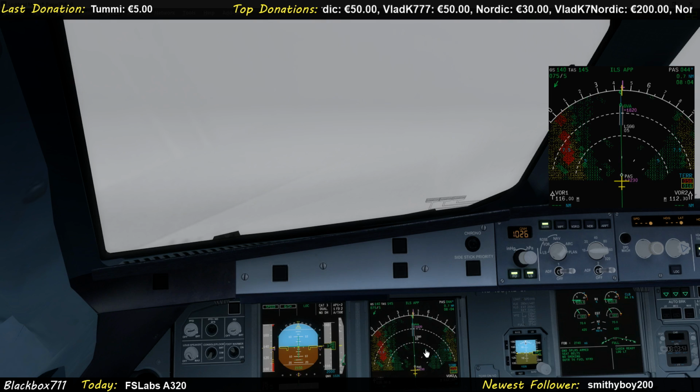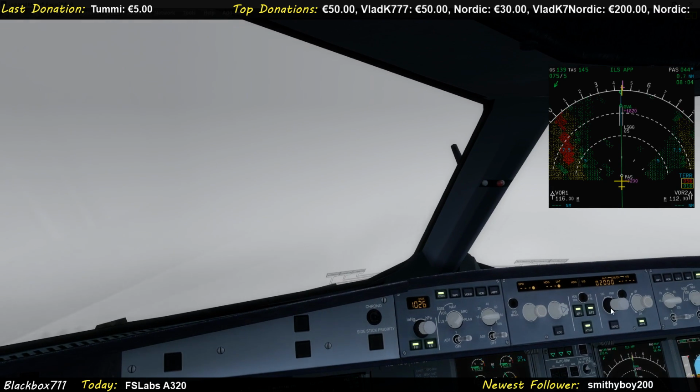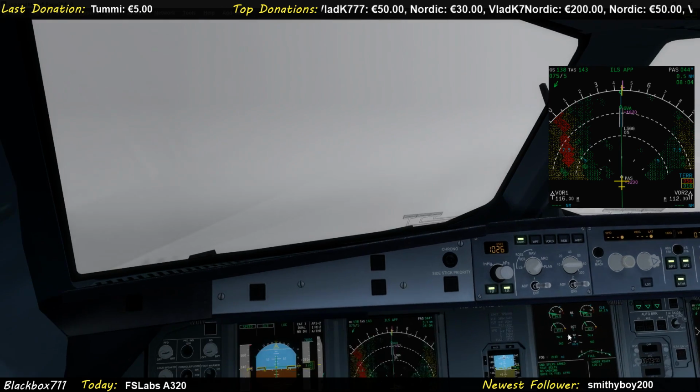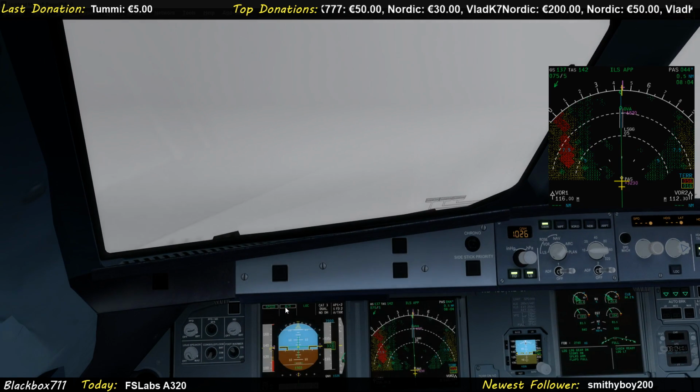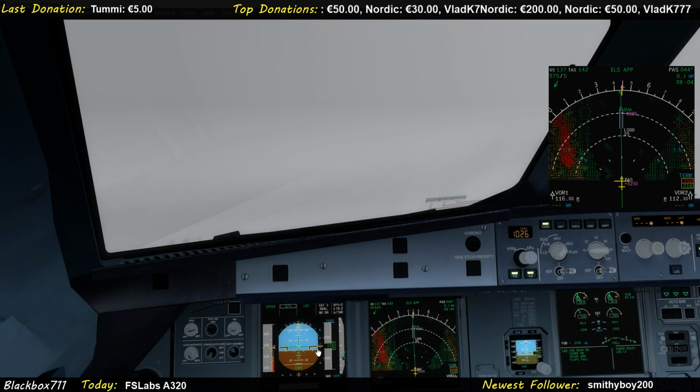Now we have glide slope star, and I can set the go-around altitude. Also very important. 70 is the go-around altitude. Make sure you set that either with Alt hold or Alt, or with the glide slope active.